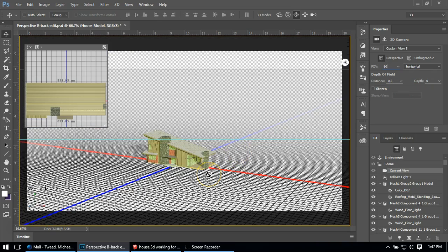You can see it zoomed the building outwards. I think you can make a good image anywhere from 45 to 100 or so, give or take, and you can go outside those. I've seen all kinds of funky drawings, but 60 is generally middle of the road. So that's going to be an angle rather than millimeters. When you do that, you might find that your building zooms in or zooms out.